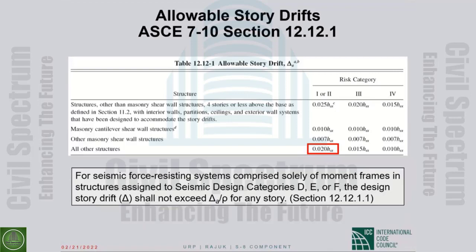So this is a major penalty for structures that employ moment resisting frames as the seismic force resisting system, no shear walls.